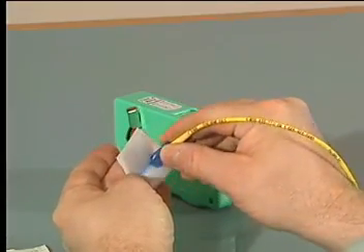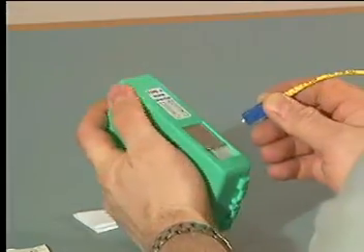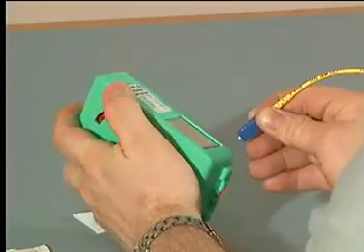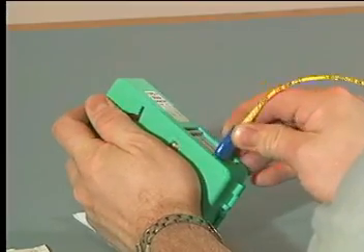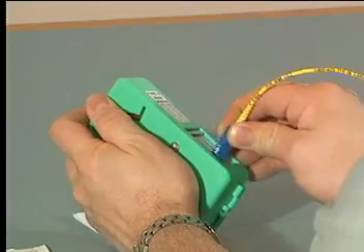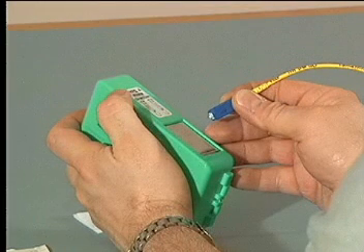Swabs, pads, and cleaning tape sections must be used only once. Use a fresh cleaner to repeat the cleaning procedure as many times as needed, usually 3 to 6 times for most connectors. Although you may consider this wasteful in cleaning materials, the cost of allowing a dirty connector to slip past you can be disastrous, especially in DWDM systems.